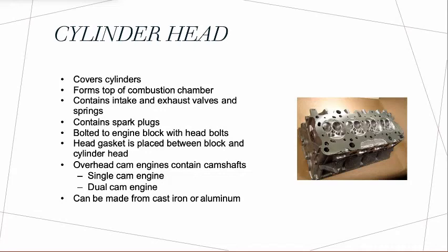And then we go to the cylinder head. The cylinder head is usually located at the top of the engine block. It serves as a housing for components such as the intake and exhaust valves, springs and lifters, and the combustion chamber. The passages in the cylinder head allow air and fuel to flow inside the cylinder while permitting the exhaust gases to flow out of it. The passages are otherwise called ports or tracts.